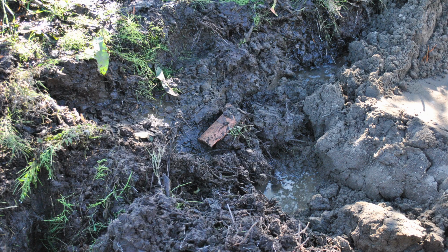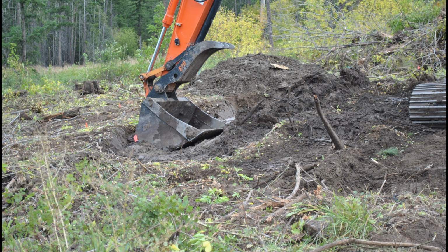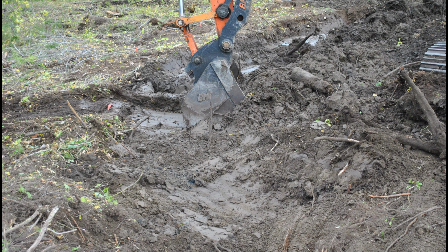It was necessary to dig a trench for a groundwater dam around the lower perimeter of each wetland we built. This is because there were pipes buried in the ground. You can see a piece of clay drain tile removed when digging the trench for one of the groundwater dams. Tim Hall is using the bucket on the excavator to compact soil that is placed in the core trench to form a groundwater dam. Clay texture soil was not available, so we placed topsoil mixed with silt loam in each core trench. The groundwater dam will help keep water in the wetlands by controlling water losses via the pipes buried in the ground and through sandy layers of soil beneath the surface.